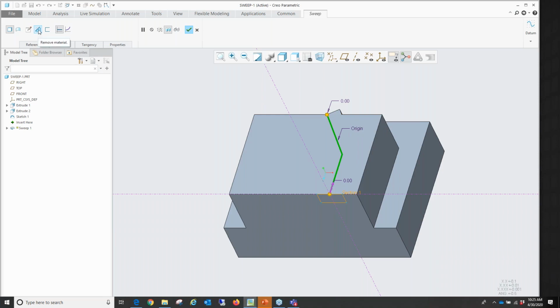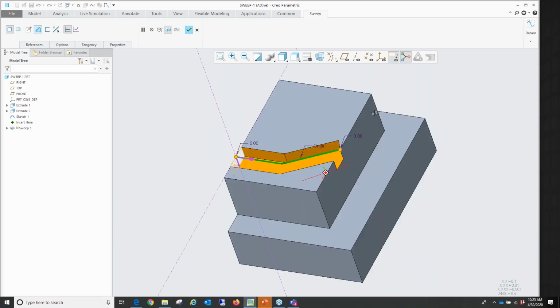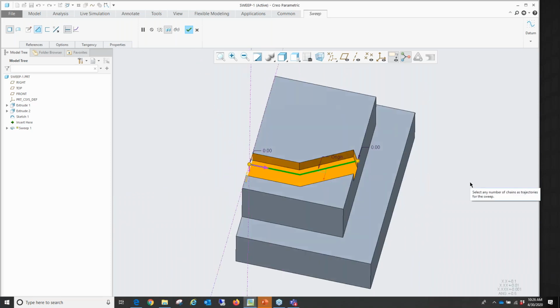So I really want to remove, so I'm just going to turn on the remove button up above and then sweep along. But you can see it doesn't quite go through the end here because I'm coming in at an angle. Now, to get that to go through the end, most likely what you would do, like we talked about, is just come up here under Options and turn on the Merge Ends. That's going to continue that into the next phase on there.